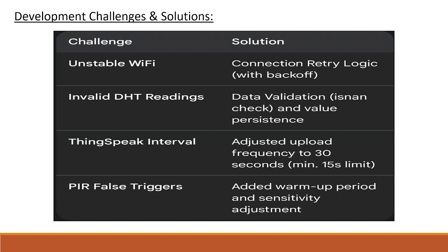ThingSpeak has a 15-second minimum interval. We adjusted our code to upload every 30 seconds. The PIR sensor had false triggers. We adjusted the sensitivity and added a warm-up period. These problem-solving experiences enhanced my debugging skills.